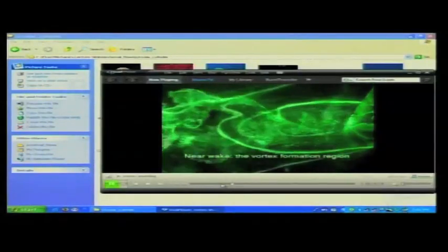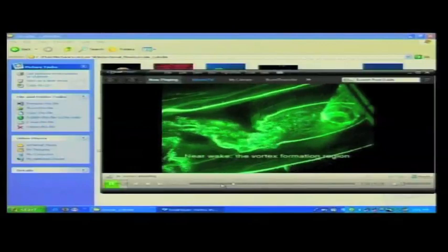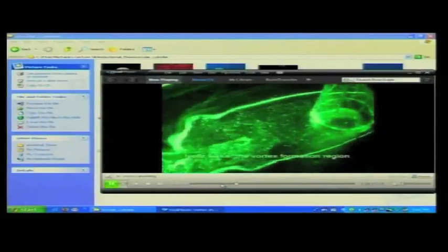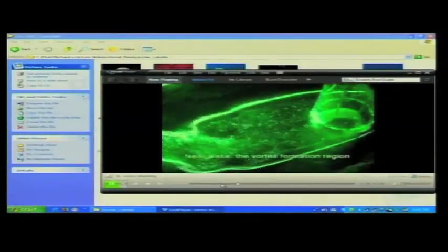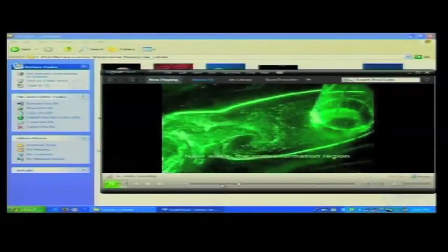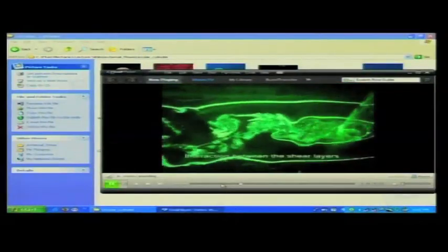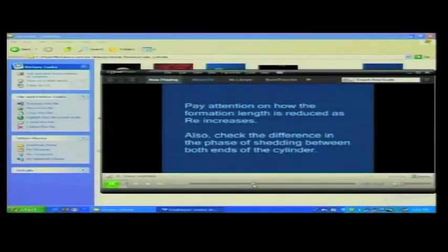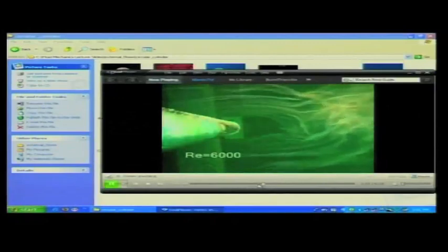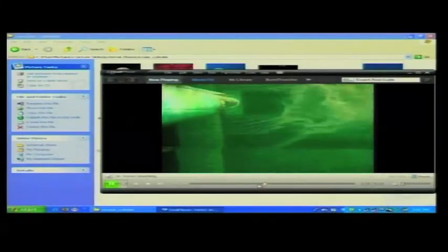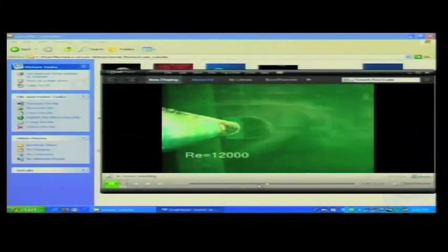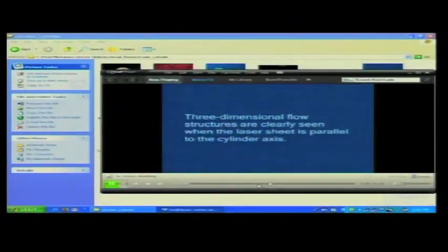Just look into this very carefully, because it gives you an idea of what sort of vorticities are there, not in a quantitative sense, but at least qualitatively the nature of rotation of these individual vortices. These vortices may be of quite complicated nature, and one of the important things that comes out of these experiments is that although the flow that came towards the cylinder was steady, there is an unsteadiness in terms of the appearance and disappearance and the frequency of the rolls which are appearing.